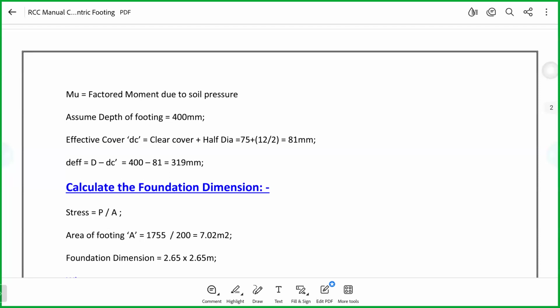See, you can place it. Doesn't matter. You can keep the foundation directly on top of soil without polythene. Doesn't matter. But the problem is, soil has different contaminants. Until the setting point, there is moisture. And the soil will have a sulfur content. Okay. And if those two collide, easily it will penetrate inside, and the reinforcement will get corroded.